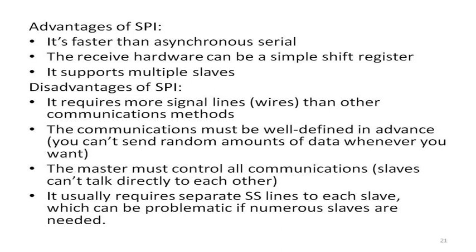It supports multiple slaves. Okay, the disadvantage of SPI is it requires more signal lines than other communication methods. The communication must be well defined in advance, and the master must control all the communication. It usually requires a separate slave select line for each slave.